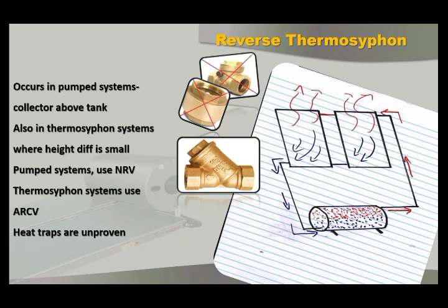And I've seen many systems where people have said to me, Richard, I can't understand it. I've just spent 30 grand on this thing, and I haven't saved a penny. Nothing is happening. And you look at it, and the guy hasn't put in a proper non-return valve or whatever the case may be. The measures haven't been put in place. Non-return valves to use here.